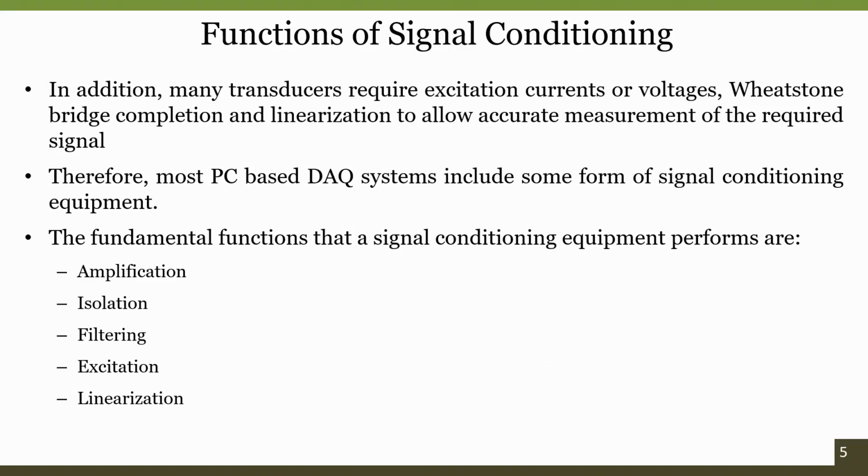But the change offered by the sensor cannot be detected by the ADC, because the ADC requires only voltage as an input, or the next stage, whatever we do, cannot identify the changes in the resistance or current or inductance or capacitance. So sometimes it is also required to convert the change in the current or the resistance or the capacitance or the inductance into voltages too.